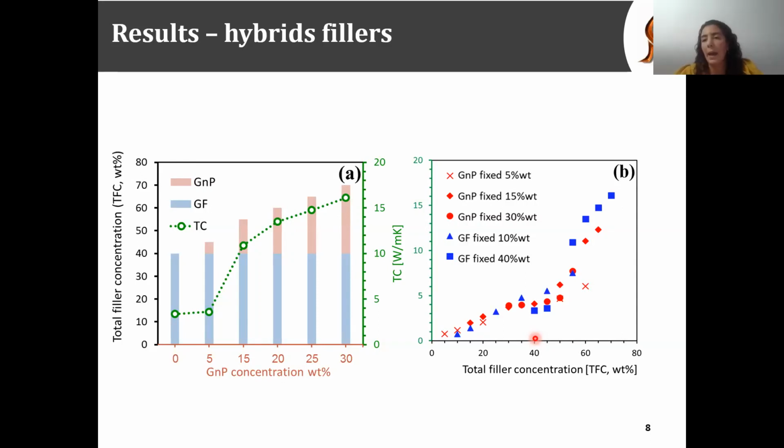Probably, as Gal Michaeli Shachar said in the beginning of the session, once we increase the amount of the filler, probably there is a reduction in the mechanical properties. The purpose of my research was to enhance the thermal conductivity as high as possible without taking into account the mechanical aspect. Okay. And there are a lot of applications where the viscosity as well as the mechanical properties don't matter, since they are casting the composite.